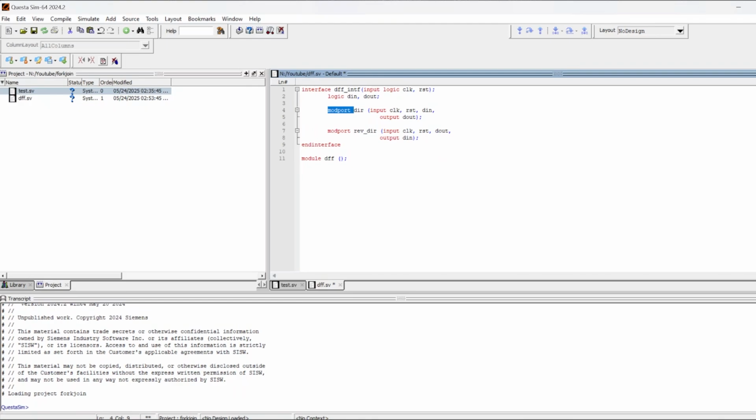So for this example, first I will just go through with the generic declaration, and then I will complete the test bench and run the simulation. Then after that, we will fiddle with the other types of declaration. So in generic declaration, you just have to use the keyword interface, just like there. And then you can mention any user-defined keyword. So for this, I will write pins. So this is user-defined. You can use whatever you want.